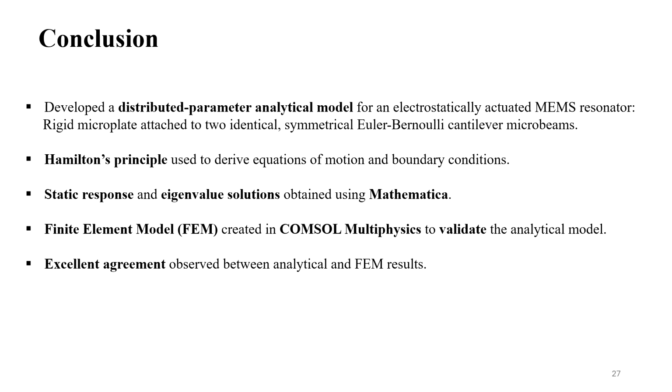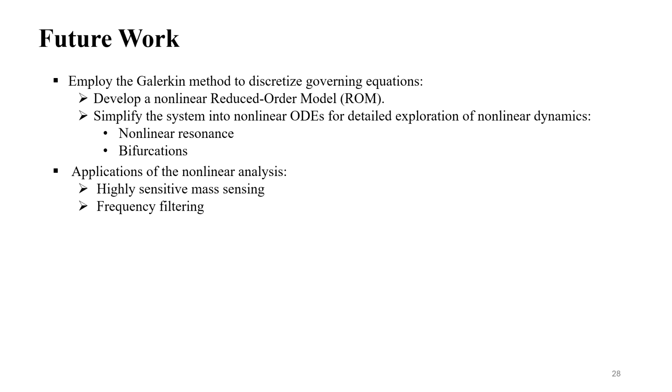To summarize, we developed a distributed parameter model for an electrostatically actuated MEMS resonator composed of a rigid plate and two cantilever microbeams. Using Hamilton's principle, we derived the full governing equations and boundary conditions. We solved for both static and dynamic responses in Mathematica and validated our model using FEM simulations in COMSOL, observing a strong agreement. Future work will focus on applying the Galerkin method to reduce the governing equations to a nonlinear reduced order model. This will allow us to investigate rich nonlinear dynamics such as nonlinear resonance and bifurcations, with applications in ultra-sensitive mass sensing and precise frequency filtering.